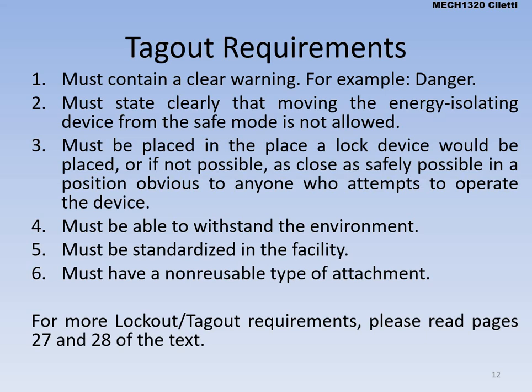Generally, OSHA wants it standardized throughout the facility, and they want a non-reusable type of attachment. That's why we don't do the tagouts in class, because I don't want to buy a bunch of those every year just to write a name on and throw away. It just doesn't make sense for us. But it should be a non-reusable type of attachment for the tagout.